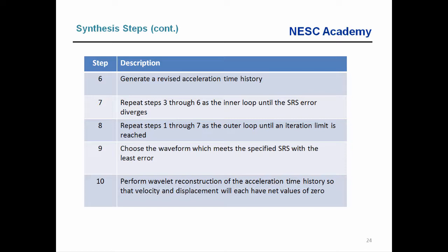So what's the problem? Here I'll tell you what the problem is. That absolute displacement due to ski slope may be up to 2,000 inches, and the true relative displacement between those 2 points might be 1,000th of an inch. So due to significant digits and truncations, if we have a very high absolute displacement, we could have some, I'll call it numerical instability, for lack of a better term, that really makes an accurate relative displacement calculation difficult.